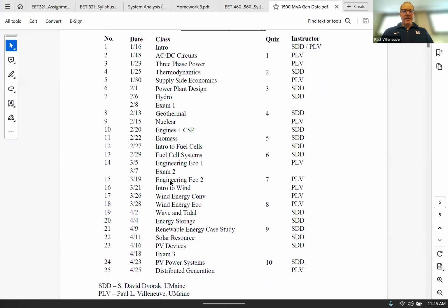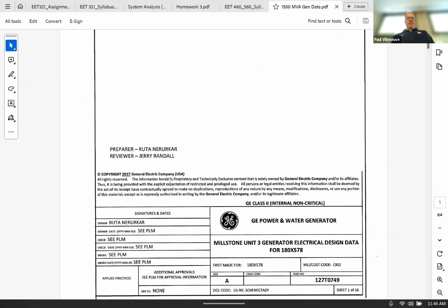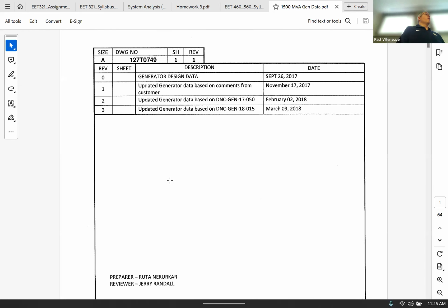This is the generator, but I don't think I have the transformer stuff in here. Yeah, so this is for a nuclear plant in Connecticut. And in Connecticut, they actually have 3 single-phase transformers connected in whatever configuration they need. Anybody want to guess as to why they have 3 there? Does it have high reliability? It's just really big. That transformer has to be able to put out almost 500 MVA at full load conditions.